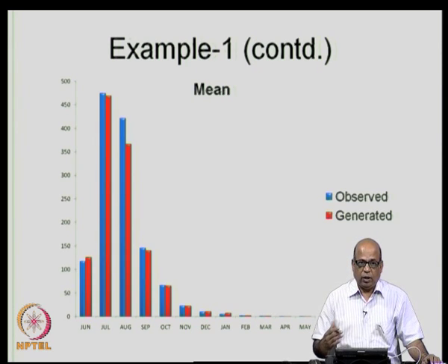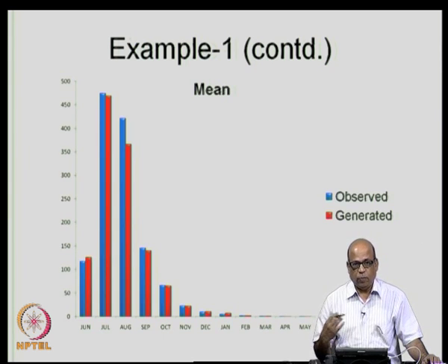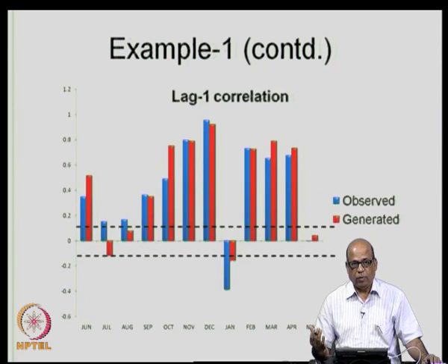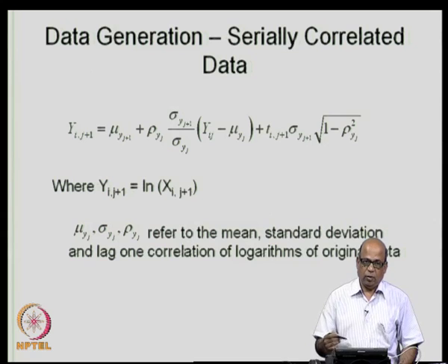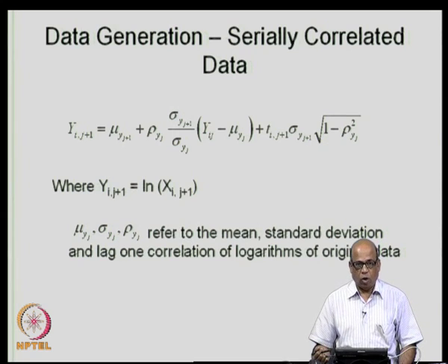Then what you must try is the logarithms of the flows. That means your original data may not be normal distribution, but it is possible that the logarithm of the flows may be normally distributed, which means that the flows can be approximated as log normal distributions.